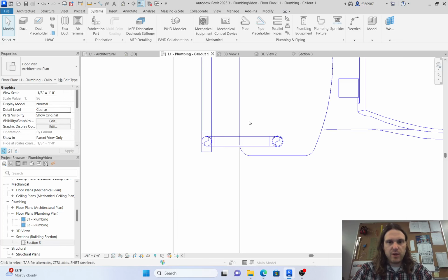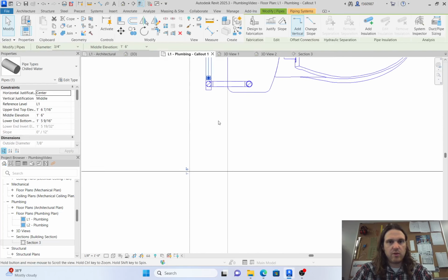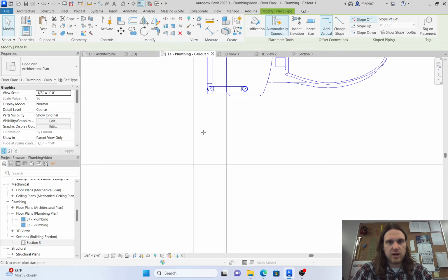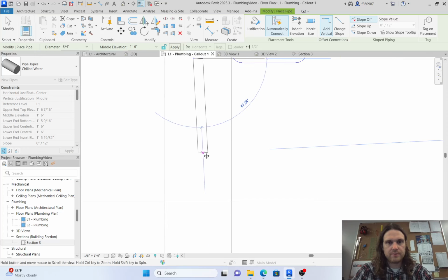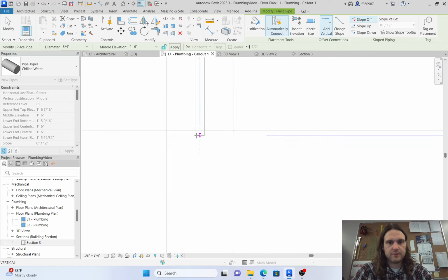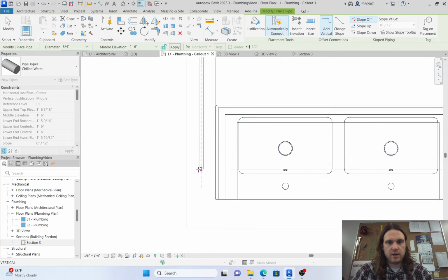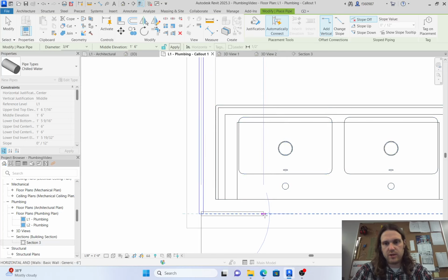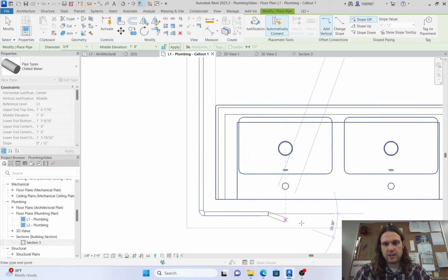Okay, so how do we do this? Plumbing call out. We get the height of this particular fitting, or the tube, the middle height is 1 foot 6 inches. So grab the pipe, come over here. All right, and we're going to come all the way around in the wall to make a corner. Hopefully, this works well. We're going to need some pipe connectors here, so let me tee this off like that.